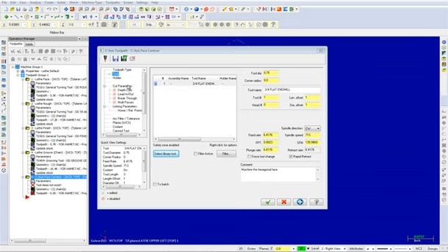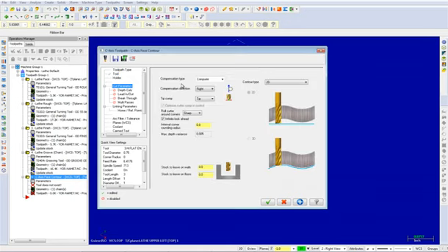Select the cut parameters and make any changes as shown. Compensation type set to computer allows Mastercam to compensate the toolpath based on the tool diameter. Compensation direction set to left offsets the tool to the left of the chain based on chaining direction. Finally, roll cutter around corners set to sharp inserts arc moves around the corners in the toolpath.